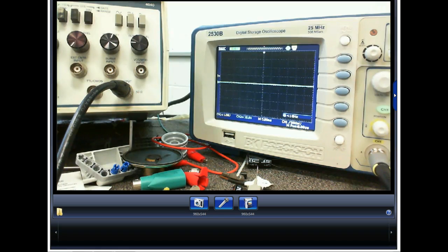So what's wrong? See here, I know this instantly. Say you're the teacher, right? The fuse is blown in the meter. Somebody blew the fuse in my meter. Since we're measuring current, and we could definitely damage the meter, the amps are fused, right, Corey? So somehow the fuse is blown in this meter. And it's the low current fuse too. It's got a high current fuse, and it's got a low current fuse. The high current fuse is 100 milliamps, so that's not much to blow a fuse, right? So somebody's blown the fuse in my meter.